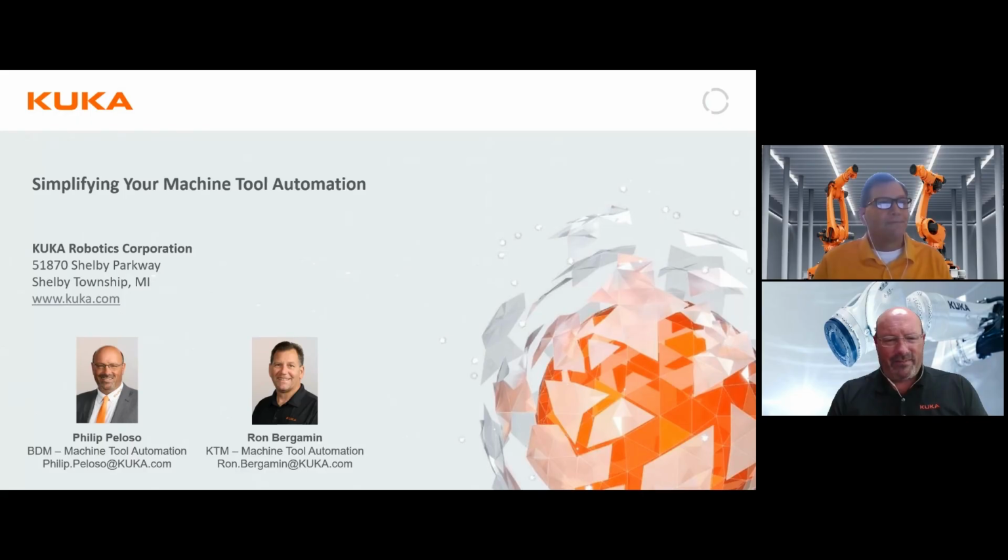Maybe it's your thoughts. Yeah, I would look at it like this. The training required will really depend on the type of application. Like I highlighted in the webinar, with MX Automation, you really don't need to know much on the robot side. So if you already have PLC or NC controls experience, it's literally one day to pick up the MX Automation side. To be honest with you, from a robot point of view, I'd rather program in our language, something I'm familiar with, but I don't know PLCs or NC controls.